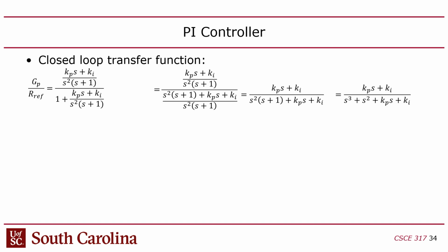Well, how do most people do that? They just randomly pick values, basically, right? MATLAB has something called a PID tuner. I have no idea how it works, or if it works. However, I found a really cheesy way to do it. So I just want to guarantee this is stable for the moment. I don't want this to blow up, right? I want it to be a stable controller. So all I need to do is guarantee that the roots are negative, have negative real parts.